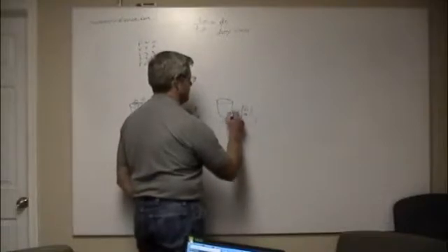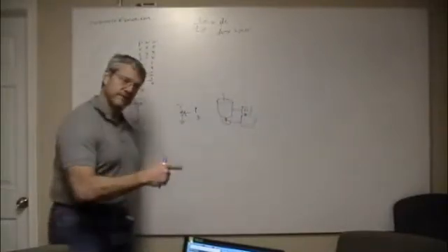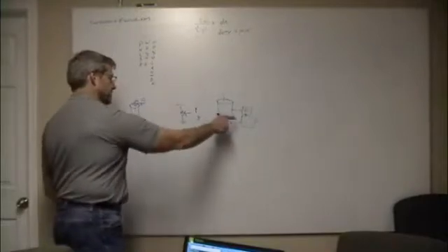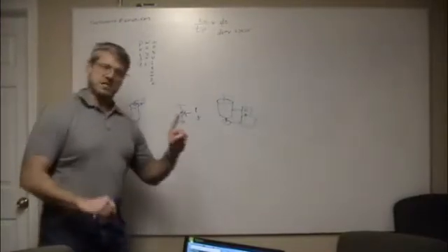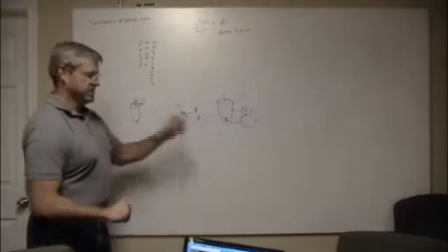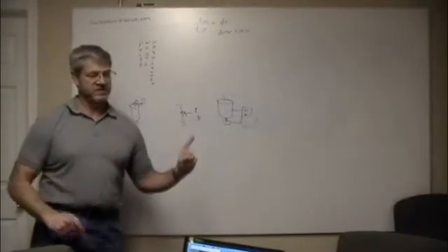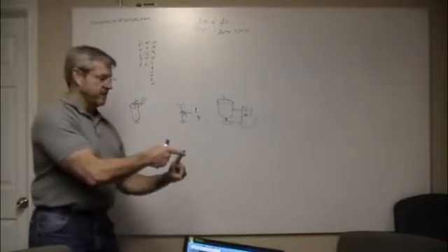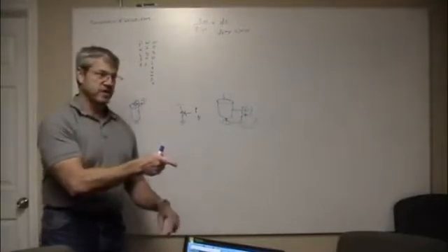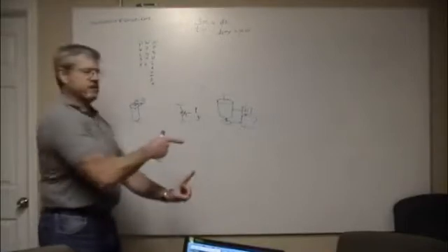And the H-bridge wants to turn the motor left or right. The control circuit monitors whatever the feedback is and says it's in this position. And you tell it, I want to be in that position, and if it's not there, it will drive to there. And then it'll stop. And then if you push on it, it's going to say, oh my God, I'm not where I'm supposed to be, and it's going to push it right back.